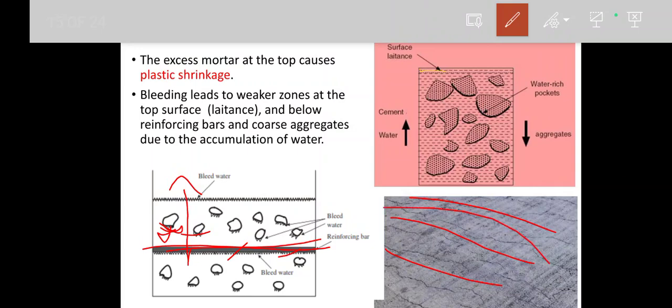See, as soon as you make the concrete, when you come the next day to make arrangements for curing, you can see long cracks that may have been created along the length of the slab. If the owner sees it, he will be suddenly shocked. Why is this crack appearing? That is all due to excessive water being added. It comes to the top surface like bleeding, and in the direction of wind, in the presence of low humidity and the high temperature of the sun. These are the factors which make this type of plastic shrinkage crack.